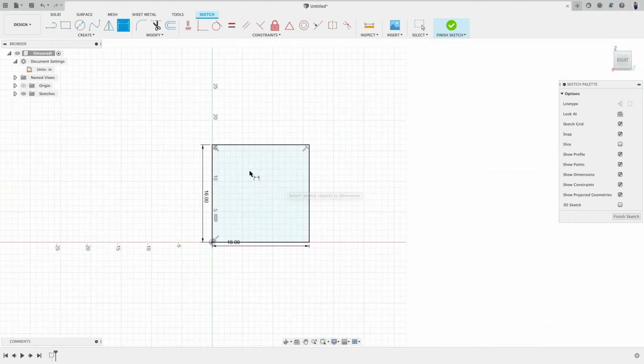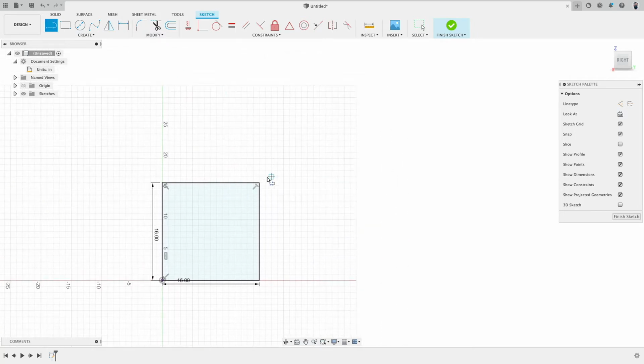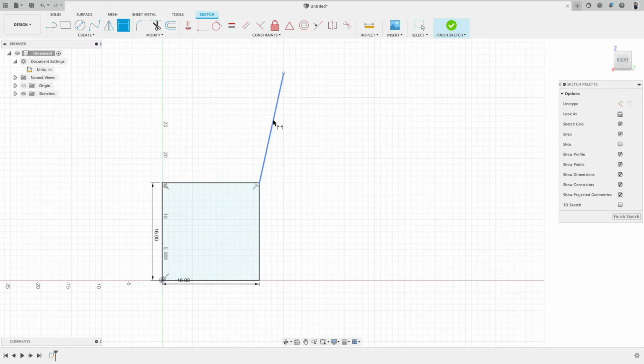And we can zoom out a little bit. So this is kind of like the seating area, height-wise, and then also depth-wise. And let's add a line. This line we make also 16 inches, but this dimension should be aligned. So there you see this is aligned now. 16 inches, very good. And the angle, let's see, what can we specify here? For example, 100 degrees. Okay.